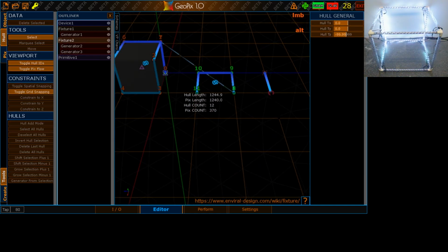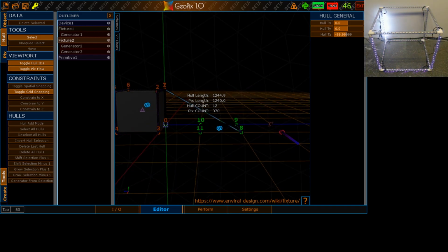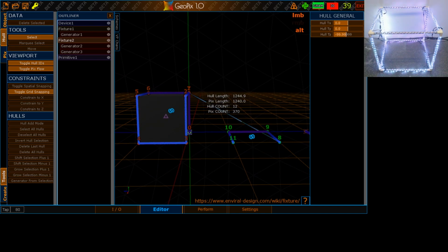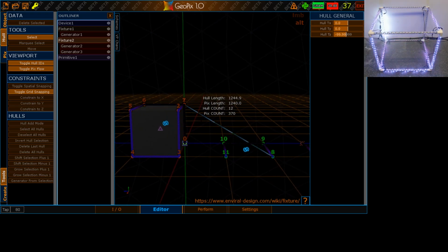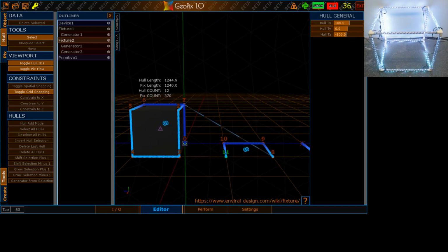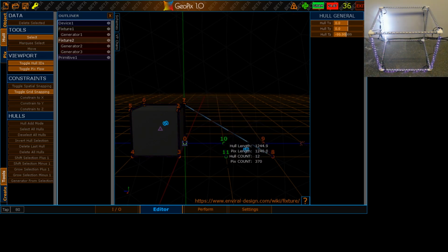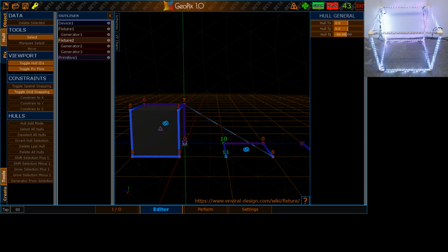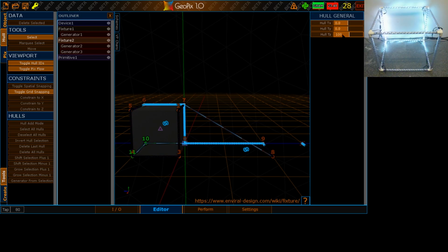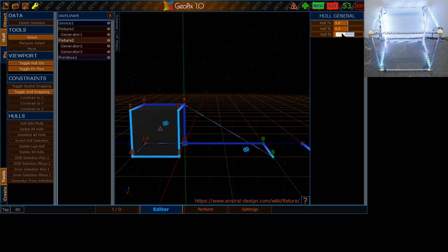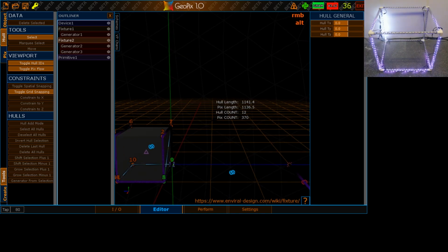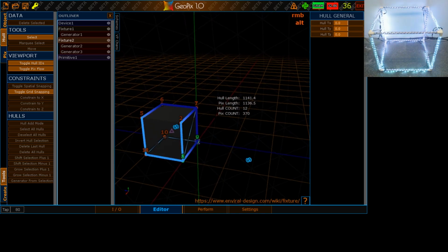So to do that, I'm going to use the translate feature in the upper right corner. So let's select just the left 2 holes, and we're going to reset that to 0 in the Z-axis, and actually that needs to go to 100. There we go. Okay, so that's 100 centimeters offset from the first pixel in the Z-axis, and we'll do the same thing for the other 2, the right side, and there we go. We now have the 111 LEDs that we just created on the bottom of the cube in the right place.